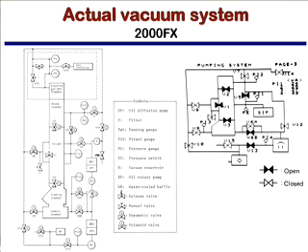And that sequence says, okay, I'm being told that I want to take the film out. So it shuts valve 3, right, so that we don't have any possibility of air leaking up into the column. It shuts valve 2, so that for sure nothing will get up to the gun. And then it starts to, often they'll show the nitrogen, it doesn't in this case, but usually what happens is they will start to flow nitrogen in order to vent the thing.